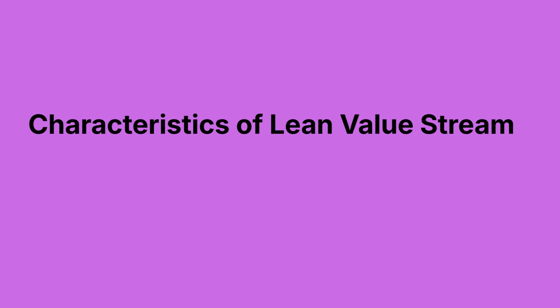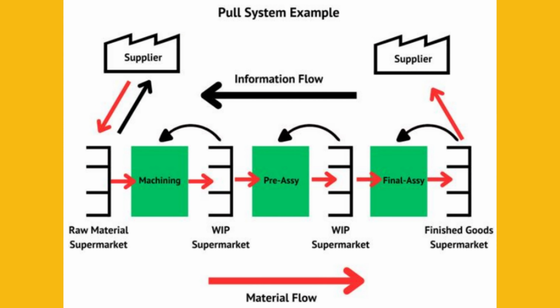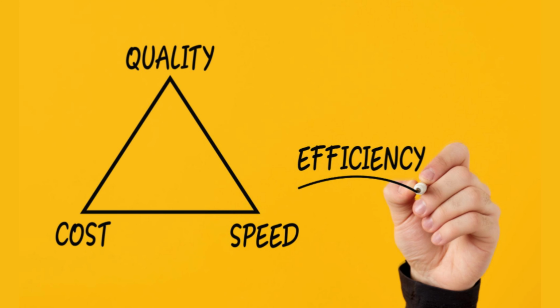All we are really trying to do in lean manufacturing is to get one process to make only what the next process needs when it needs it. We are trying to link all the processes, from final customer back to raw material, in a smooth flow without detours that generates the shortest lead time, highest quality, and lowest cost.